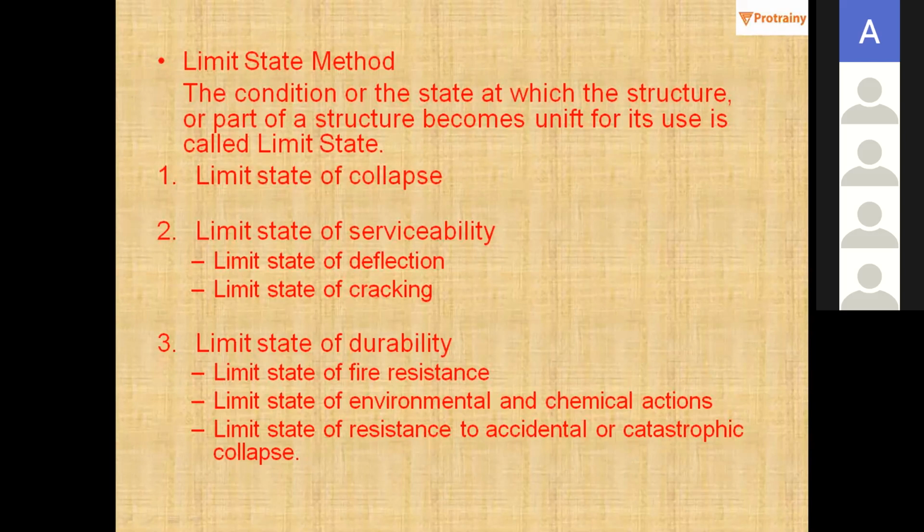Next one is limit state of cracking. You can achieve this limit state by applying proper detailing as per the code. Last one is limit state of durability, limit state of fire resistance, limit state of environmental and chemical actions, limit state of resistance to accidental or catastrophic collapse.